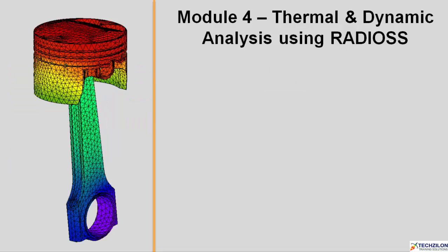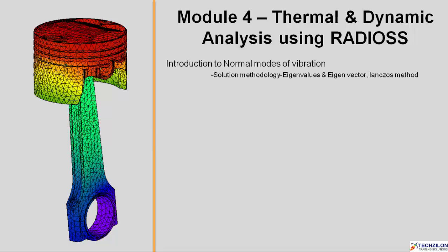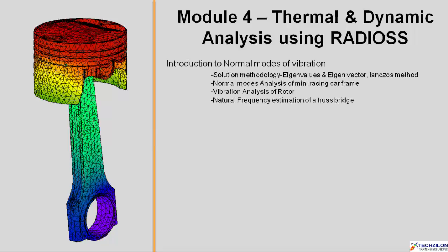In Module 4, you will learn thermal and dynamic analysis using RADIOSS. You will be introduced to normal modes of vibration, under which you will learn solution methodology, which consists of eigenvalue, eigenvector and Lanczos method, normal modes analysis of mini racing car frame, vibration analysis of a rotor, natural frequency estimation of a truss bridge, and modal analysis of a brake disc.